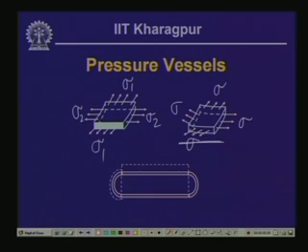That means the stress, or the pressure exerted by the content of the spherical vessel, is being resisted by the vessel in all directions. Now, as we have seen in both cases, both for the cylindrical as well as the spherical vessel, the pressure exerted on the curved surface is normal to the surface, and since the wall is thin, the variation of the stress across it is negligibly small, and we disregard that. Hence we have a biaxial state of stress in terms of sigma 1 and sigma 2.